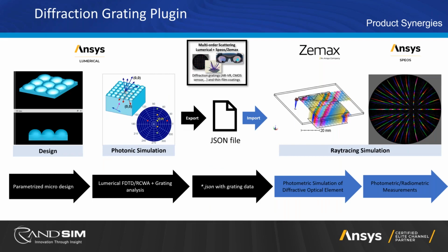So I just wanted to highlight in particular this example. If you're designing some type of optical system within Zemax, often you're trying to make them smaller and smaller. And when you're doing that, you need to introduce components like nanostructures or microstructures. The thing is, when you're starting to get within these very tiny structured optics, you can't always design them purely with ray tracing tools. So we have this workflow that allows you to simulate, for example, this diffraction grating.